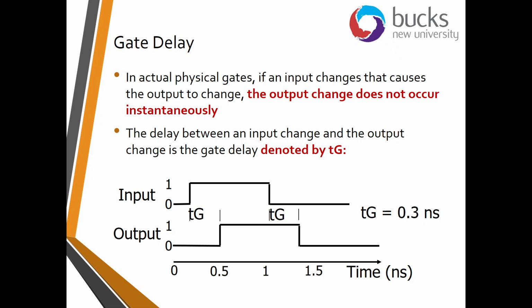So we have time at the bottom in nanoseconds, incredibly fast, but we can see that as we are changing inputs, the output of the circuit is not perfectly aligned, it's not instantaneous. There is a gap of about 0.3 of a nanosecond between input coming in and output coming out, and that's just something worth noting in terms of the operation of these electronic circuits. Electronic circuits are not instantaneous things. There are physical limitations to how they respond.